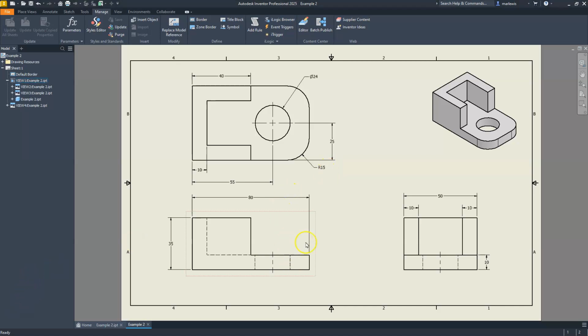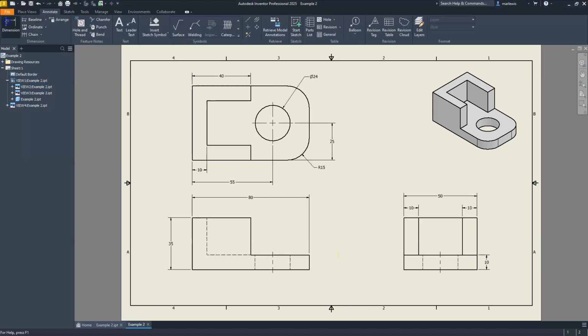As far as showing you where the dimension style would be, let's click back on Annotation. When I go to Dimension, you're going to see it appears by style, right? So by default, if I'm in millimeters, the standard is here. This is by the style because that's what I chose. Now I can change which standard I want by selecting it here, but by default, if I create a dimension from here to here and place that dimension, it's going to be on that standard style, which in our case is the millimeter one, right? But if I was using inches by default, it would select the inches.